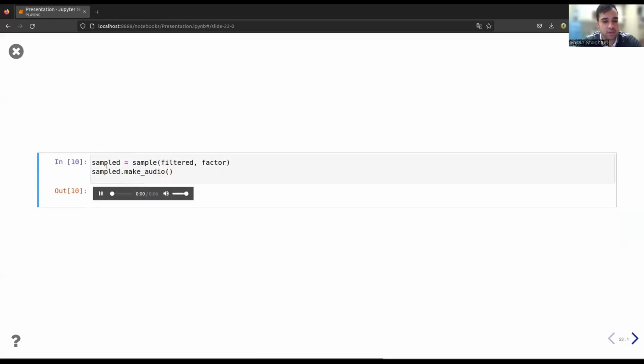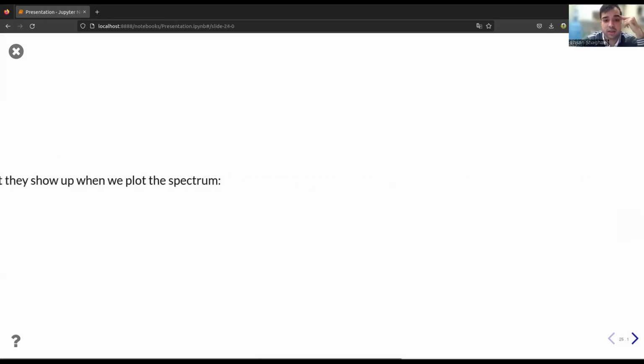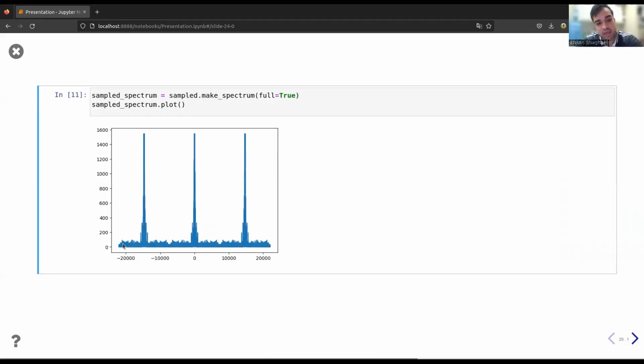So you basically hear more corrupted noises within your samples, maybe more low frequency and very, very high frequency noises within the original sound that we actually heard with the higher sampling rate. And if we show the spectrum, we see some aliased frequency within this range, exactly right after our sampling frequency spectrum.